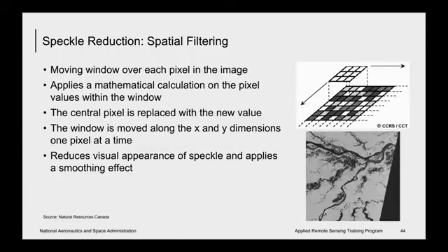If you are looking at large areas for mapping or other applications over large areas, then speckle reduction techniques may be more appropriate and acceptable, where you do large-scale averaging, or you'd use larger multi-looking or larger windows for spatial filtering. So I personally prefer to do a multi-looking and just averaging.